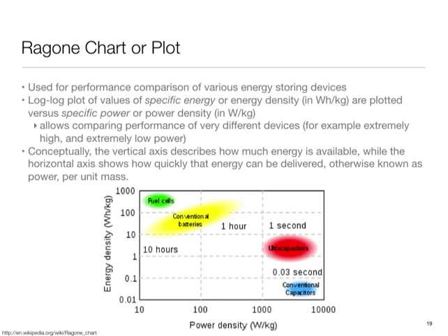But conventional batteries are very great at energy density. They can store a lot of energy, but they are not that great in power density. They cannot supply a whole lot of current. Capacitors excel in another dimension. Capacitors are very good at supplying that burst of energy, but they don't store a whole lot of energy, orders of magnitude lower. But they are shifting up.